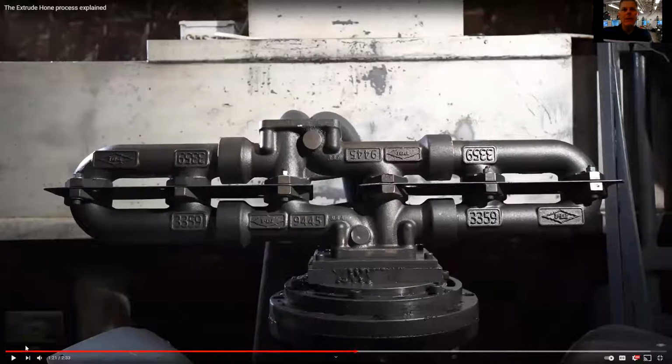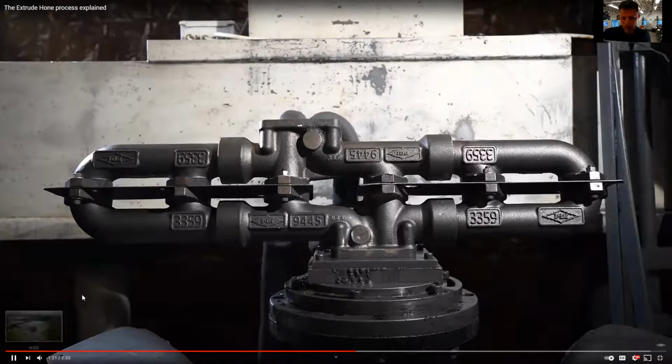If you think about it, it's flowing the same path that air would want to flow too. So it's basically smoothing out the transition, or all the sharp transitions that are inside that casting, and it's going to make the air want to flow a lot better, giving you more power. It's giving you less frictional losses on the walls of that part, allowing more air to flow through the motor, allowing you to burn more fuel and air and make more power, right? So there we go.